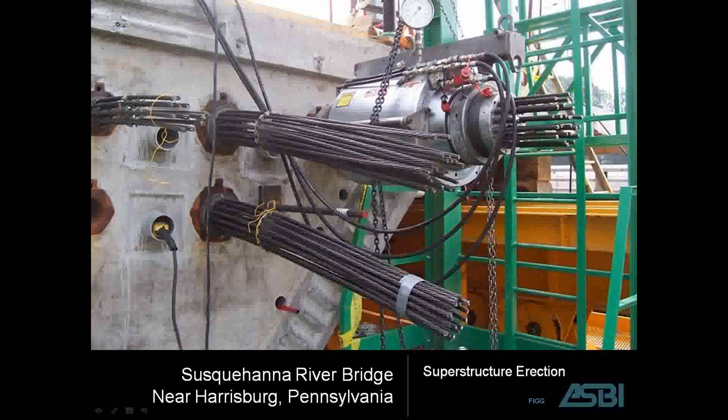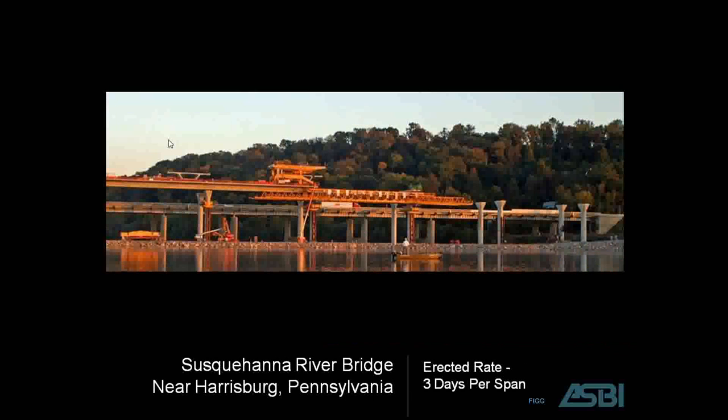The post-tension ram is applied, and then the tendons are stressed up to the required load. You can see here on the left side, there's an empty post-tension duct, and that allows for future PT. And then you can see some open holes, one with a light that's been placed in there. This hole here provides for the continuity tendon for the span that has not been erected yet from where we're taking the photograph. There'll be a span there, and these tendons stitch over the support to provide continuity.